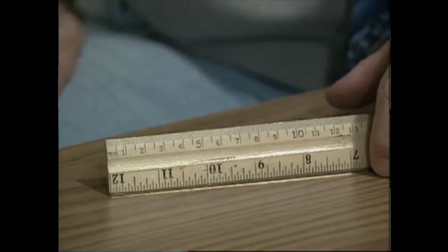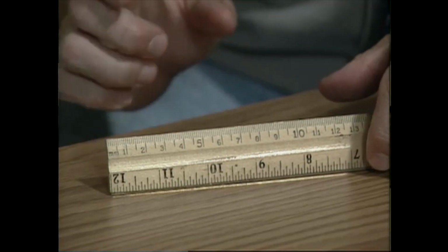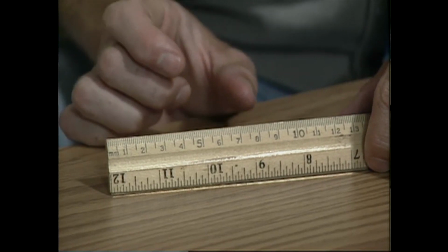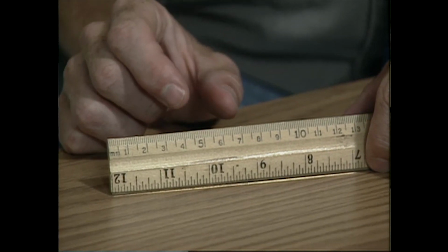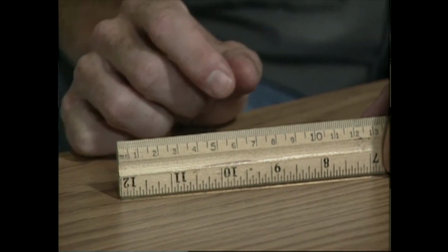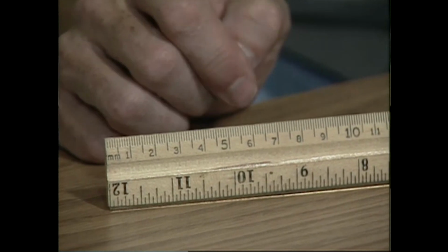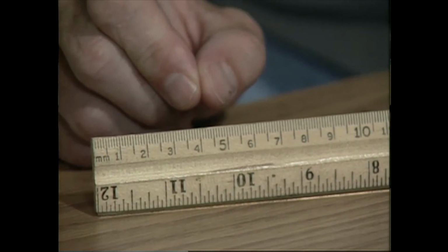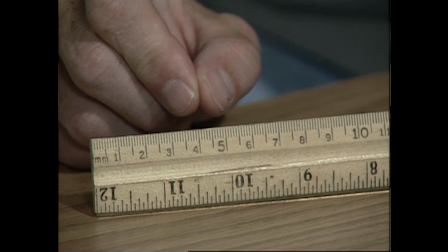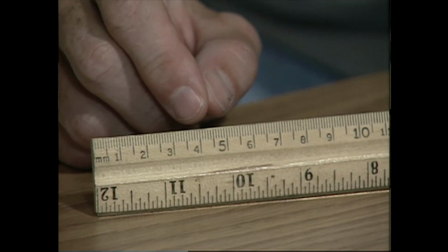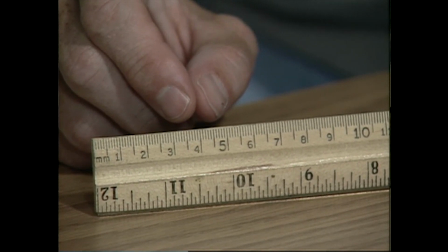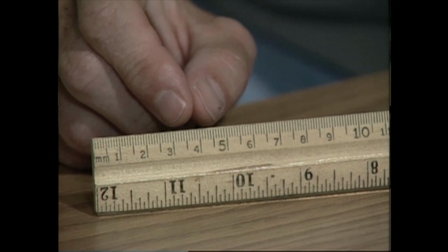Perhaps the simplest method for measuring distance is by the use of calibrated length scales, such as this tape measure or this ruler here. Now, the maximum resolution you can get with a calibrated scale, such as this ruler, depends on the minimum graduation of the scale. You can see this ruler is calibrated both in centimeters and in inches, and the finest graduation of the centimeter scale is 1 millimeter, so this system is really only usable for accuracies down to, say, a fraction of a millimeter.